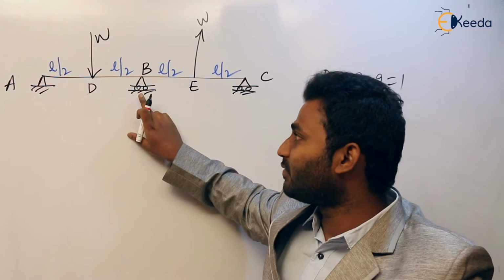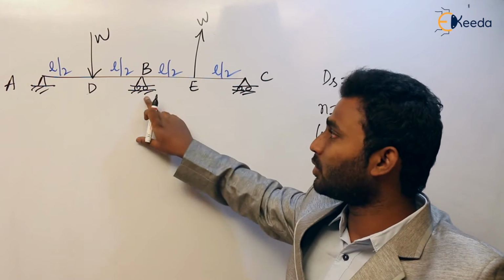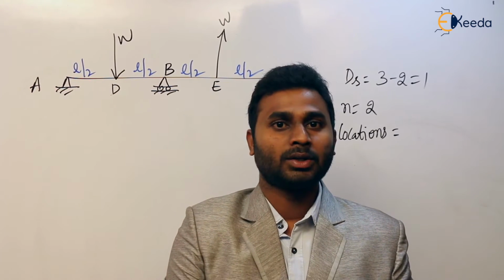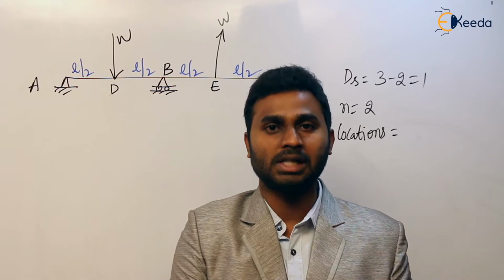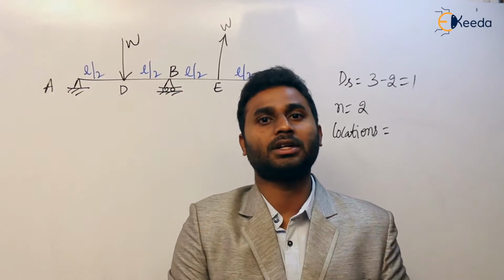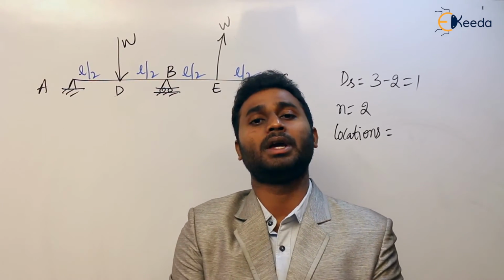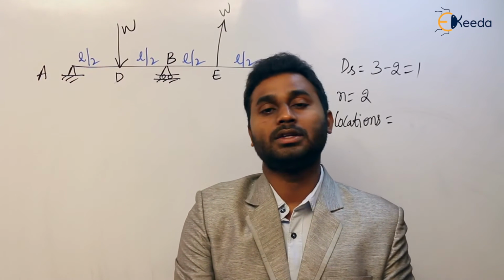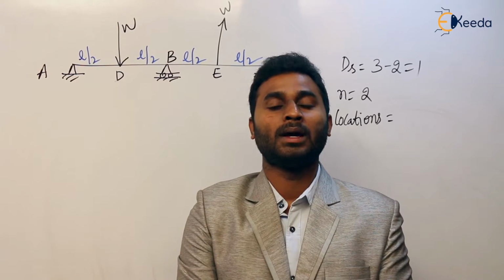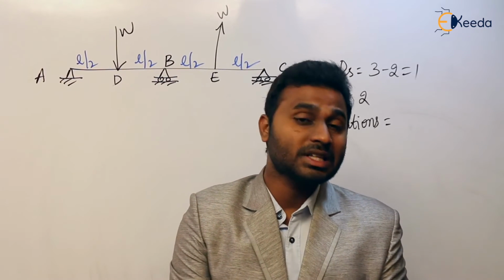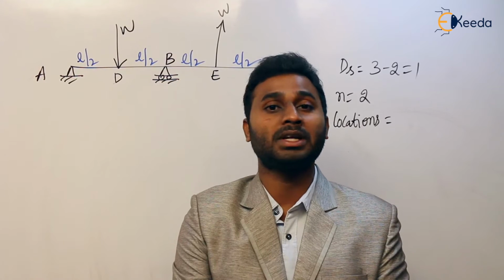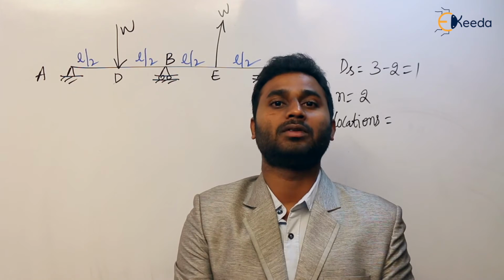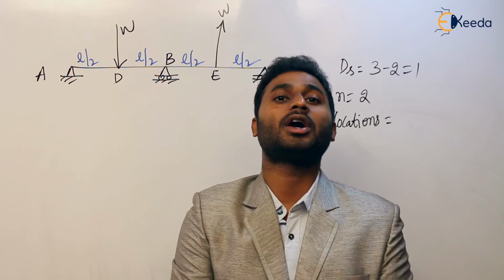The reason is, if a hinge or roller support is at the ends, then it is already a hinge and cannot take any moment. In strength of materials, you have studied that in drawing the SFD and BMD, the bending moment at simple supports, either hinge or roller support at the ends, is 0. But if the very same support is in between the span, then the bending moment is not 0. The summation of moment may be 0, but there acts some bending moment, which is hogging. So always at supports, hogging moment will act.